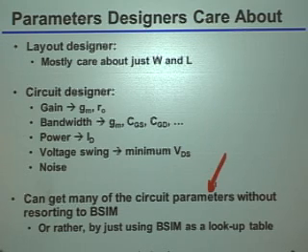And then the only way we're going to use SPICE is as a lookup table to map from these circuit level parameters you actually care about into what the actual device dimensions need to be. Okay? And we'll see that once we've done this, it's a pretty powerful methodology because it lets you very quickly do designs in a very productive way.